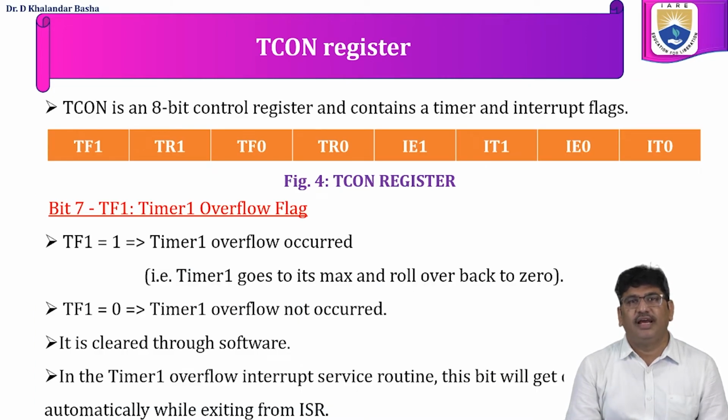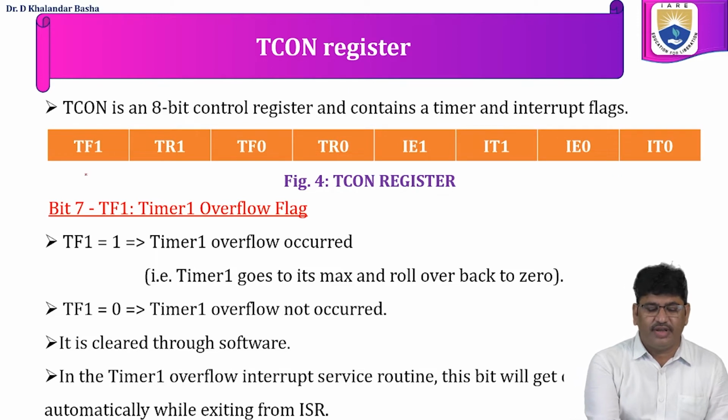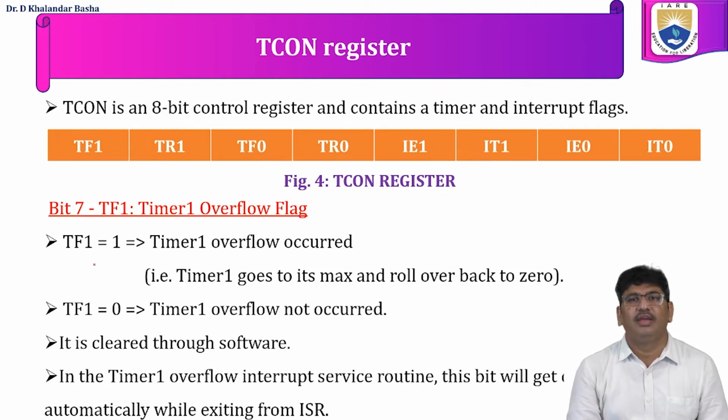The next one is the TCON register. For configuring and controlling the timers, we have to program the TCON register. TCON is an 8-bit control register and contains the timer and interrupt flags. The various bits here are, first, TF1, which is the timer 1 overflow flag.